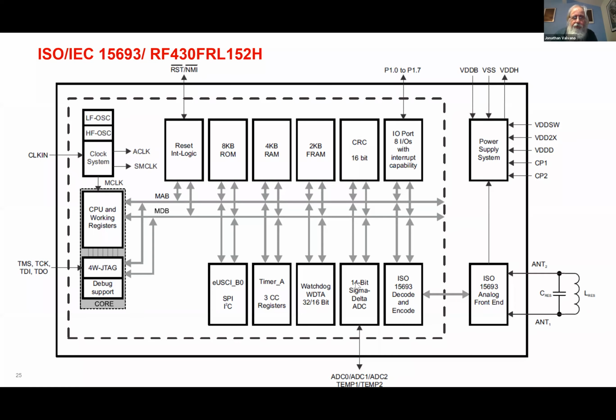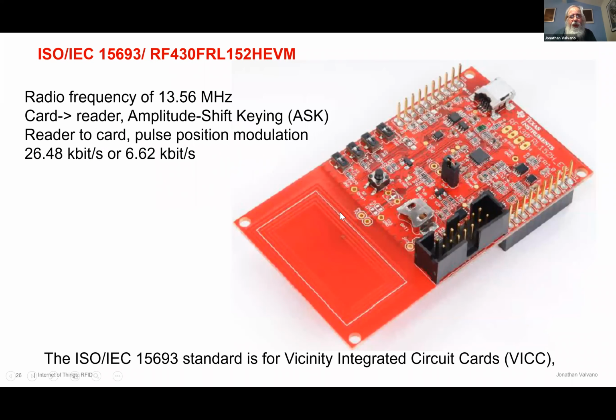All right, so I showed you this. Now we're at 13 megahertz. That's a development board, and the big black chip in the middle is the MSP430 with this radio frequency modification to it. You just line up the two coils, the sensor coil and the reader coil, in order to get it to communicate. Let me show you the encoding.